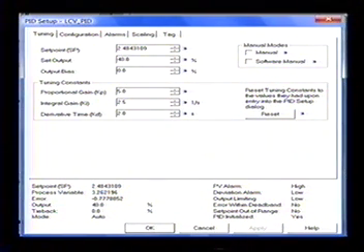is go into automatic mode, start the unit up, the pump would start, the inlet valve would open, and the tank would start, the valve would start modulating open and closed. And you would set your D to 0 and your I to 0, and you'd start increasing your KP. Increase your KP until the output valve starts to move, right? It's just going back and forth, open and closed, right? Once you find that value, whatever that value may be, cut it in half.